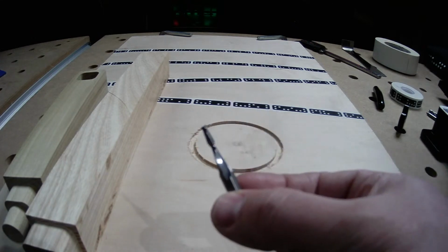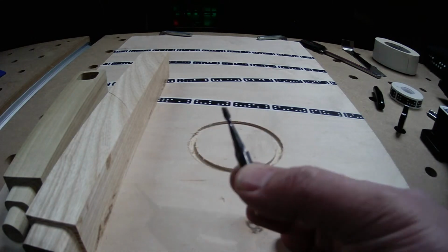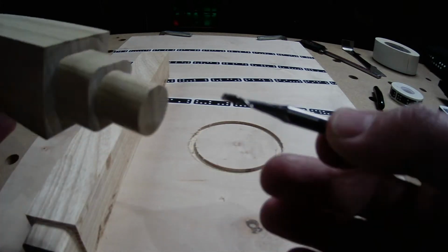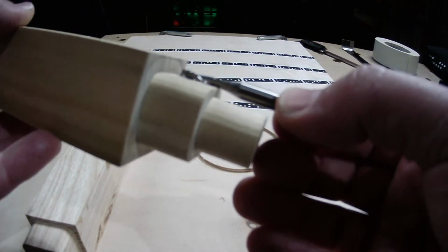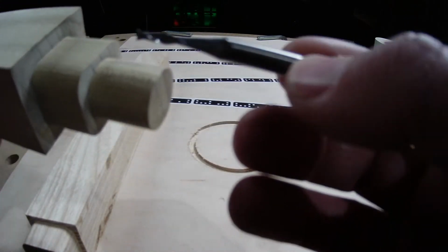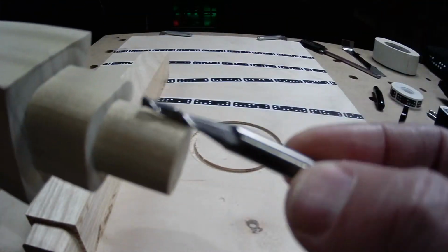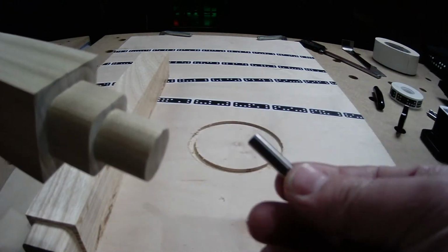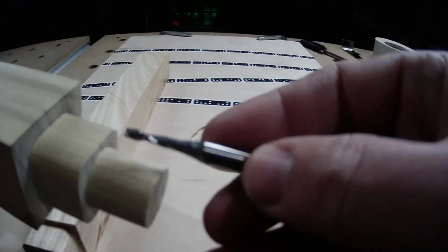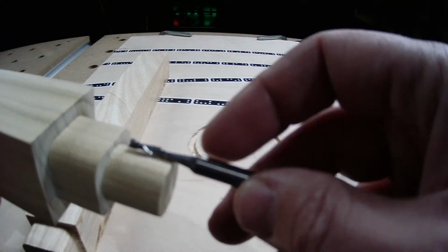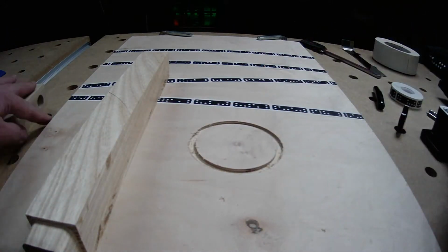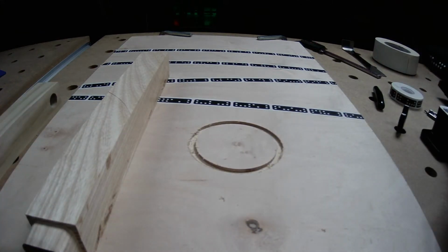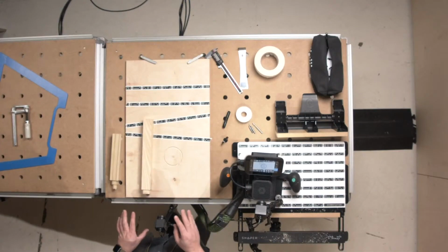to work with the standard collet that comes with Origin. And so that little trick won't work here, because you're going to end up potentially running into the shank. You could figure out how to make it work if you did your math right. That one's just a little bit trickier because the diameter of the shank of the bit grows here. You can see there's that gradual lead out that it grows into the shank size. So watch out for that. But yeah, it is fun to play with. Just know that 3/4 of an inch isn't necessarily the end of the line.